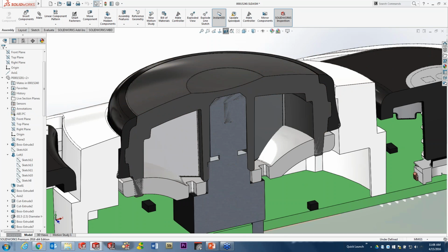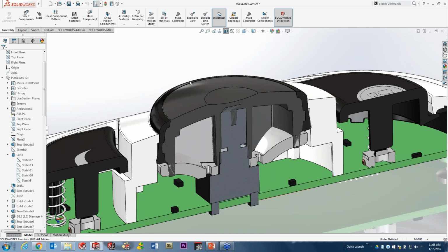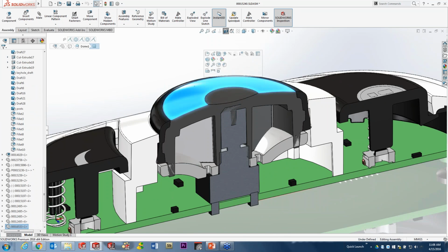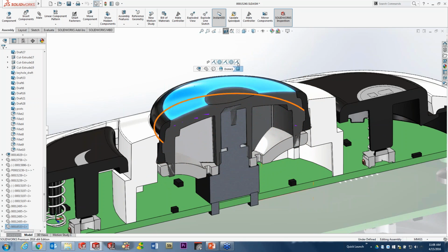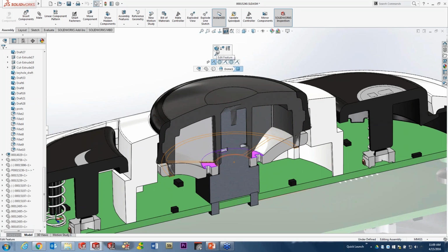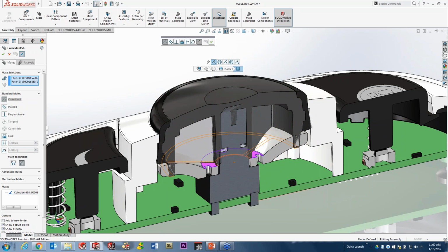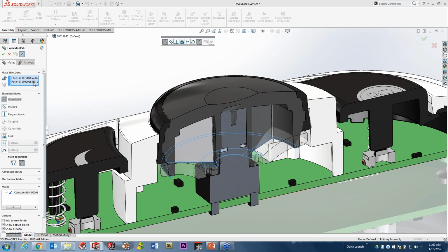Well, this is where breadcrumbs, again, are very, very convenient. By selecting the component and really not even worrying about the depth and the hierarchy of the feature manager, I can tap that D key and bring those breadcrumbs right over here and see that we have faces, features, and then the part with all of its mates right here conveniently located. Now I can actually click the mates and action on those. So when I go ahead and actually edit the feature, this gives us the opportunity to switch things up.